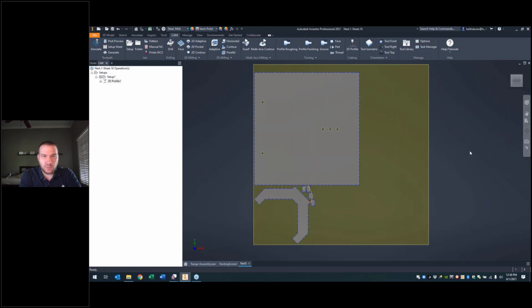And when we use that from sources tool, we can import assembly files and all the sheet metal components within them, or extruded material within them. We can also import individual sources as necessary to try to fill up a sheet as required, or as parts are necessary. If we did have extra stock material or scrap pieces that we wanted to try to utilize, we can add those to the material library, or to the process material library, and have it use those as necessary as well. Or if we have to order specifically larger sheets and things of that nature, we can do that.